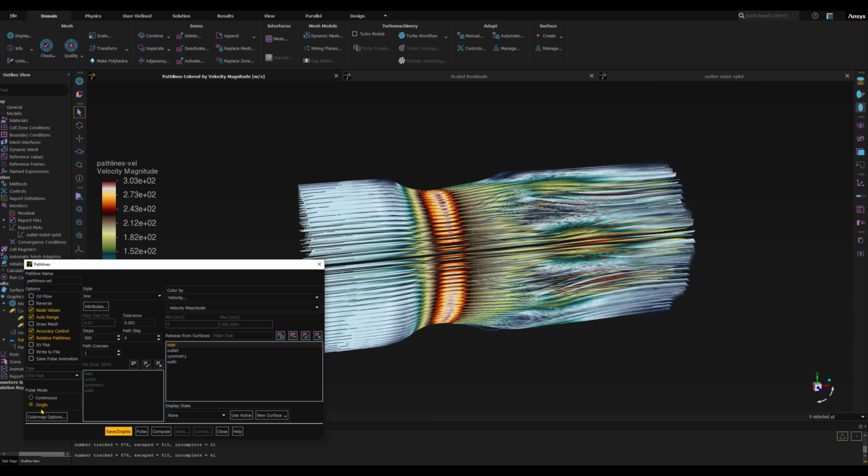So you can see here this path line. You can select different options and try by yourself. This is the continuous path line. I will select this one this time, and you can also modify this path line. For example, you can change the type to line or line arrows, or different options for skipping some of those.